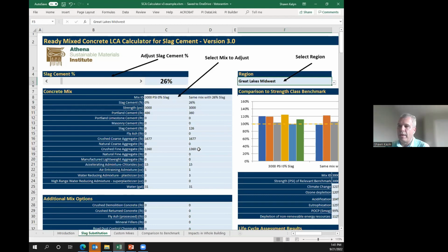There are a lot bigger impacts and a lot bigger CO2 emissions and acidification that you'll see when you're doing it with a truck versus having most of that cement either railed or brought in by barge. Just those efficiencies of the rail and the barge greatly impact those numbers. And that can also impact the numbers, especially on the aggregate end. The aggregate material may not have that much of an impact, but the moving of those materials can have a big impact.